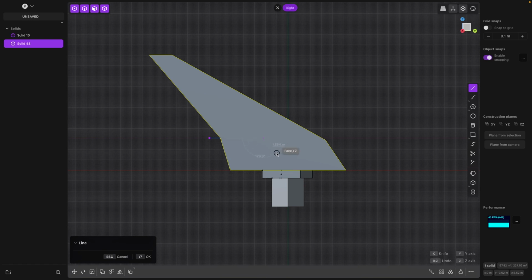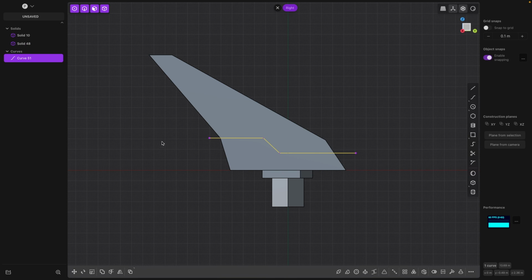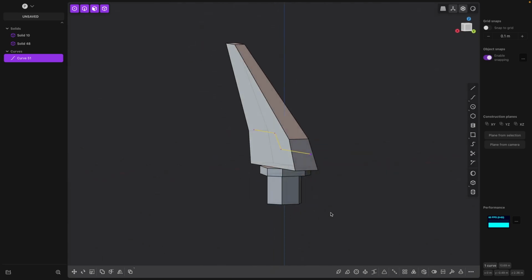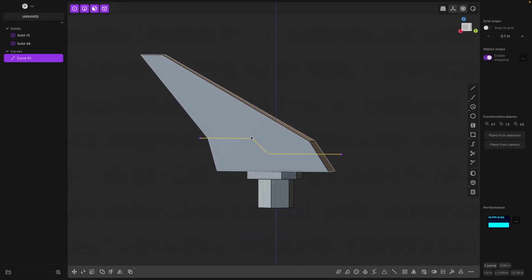I want to go down an exact 45-degree angle here, so I'm going to hit tab twice to edit this angle and make it 135. And so that locks me into what I know is going to be that 45-degree angle that I'm after. We'll do this, and then we'll drag it out here. So I'm just making sure this is outside of my shape on both ends. So now again, looking from 3D, it kind of runs through the middle of this object, but this is the center of our line.